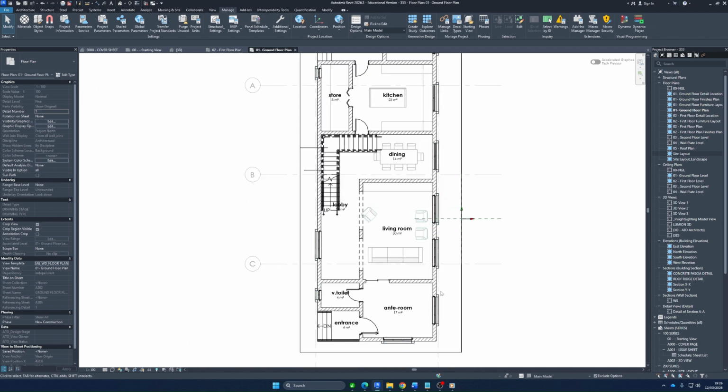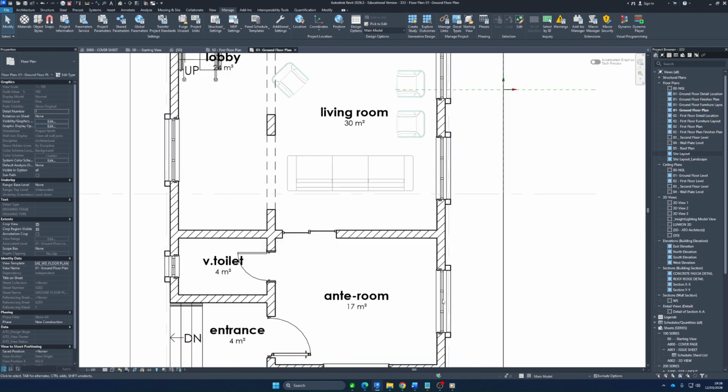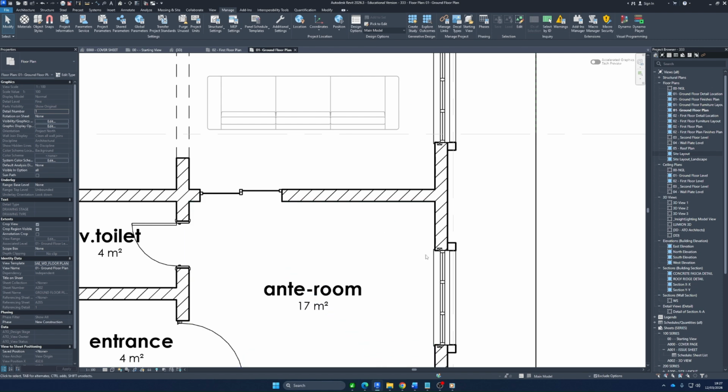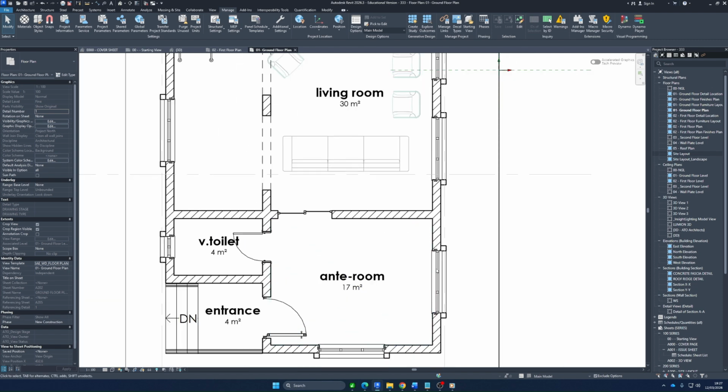Now you notice also another thing. I selected 1, 2, 3 windows. I never selected this guy, but you can see that this guy is now in an option set, in that option set. Why? Because the host is now in there. So that's how windows and doors work. Same thing if you are doing phases. Okay, if you get rid of the wall, the door goes with it. If you get rid of the window, you get rid of the wall, the window goes with it, because those elements can't stay on their own. So if the host goes, they go also.